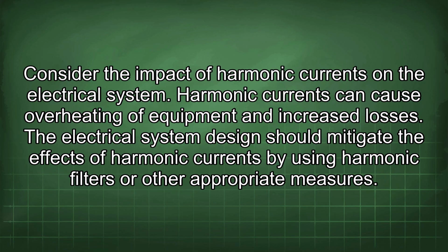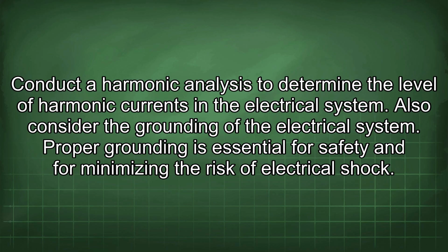Consider the impact of harmonic currents on the electrical system. Harmonic currents can cause overheating of equipment and increase losses. The electrical system design should mitigate the effects of harmonic currents by using harmonic filters or other appropriate measures. Conduct a harmonic analysis to determine the level of harmonic currents in the electrical system.